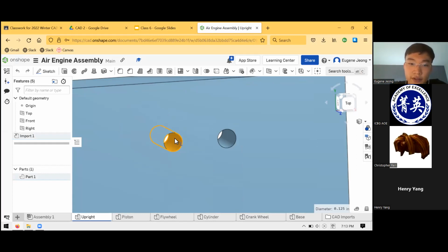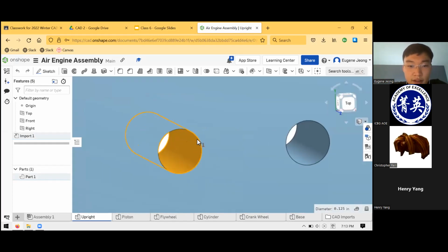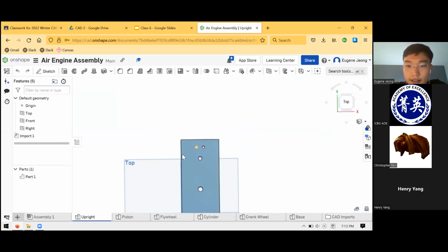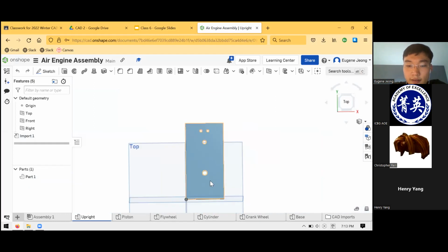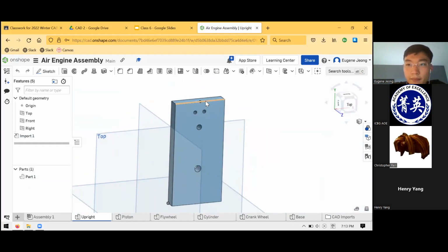You can just add another hole in the same location, but for the model, it's not really necessary, and I didn't do it. Wait, what's the tap clearance? Is it just 3? Tapped and clearance means there are no threads. Oh. Clearance means it's big enough for the screw to just slide in and out of. Tapped means it has threads, so you twist the screw into it.